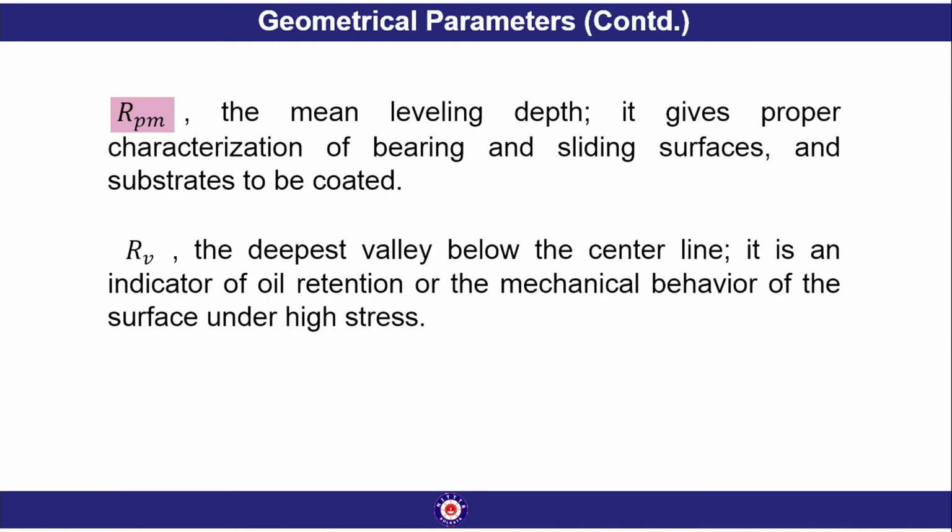Then comes Rpm, the mean leveling depth. It gives proper characterization of bearing and sliding surfaces and of course, substrates to be coated. Then the last parameter is Rv, the deepest value below the center line. It is an indicator of oil retention or the mechanical behavior of the surface under high stress.